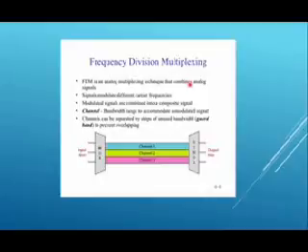The color information and picture are transmitted by way of frequency division multiplexing techniques. FDM, or frequency division multiplexing, is an analog multiplexing technique that combines analog signals. Signals modulate different carrier frequencies. Modulated signals are combined into a composite signal. The channel is the bandwidth that accommodates a modulated signal. Channels can be separated by strips of unused bandwidth, called guard bands, to prevent overlapping.